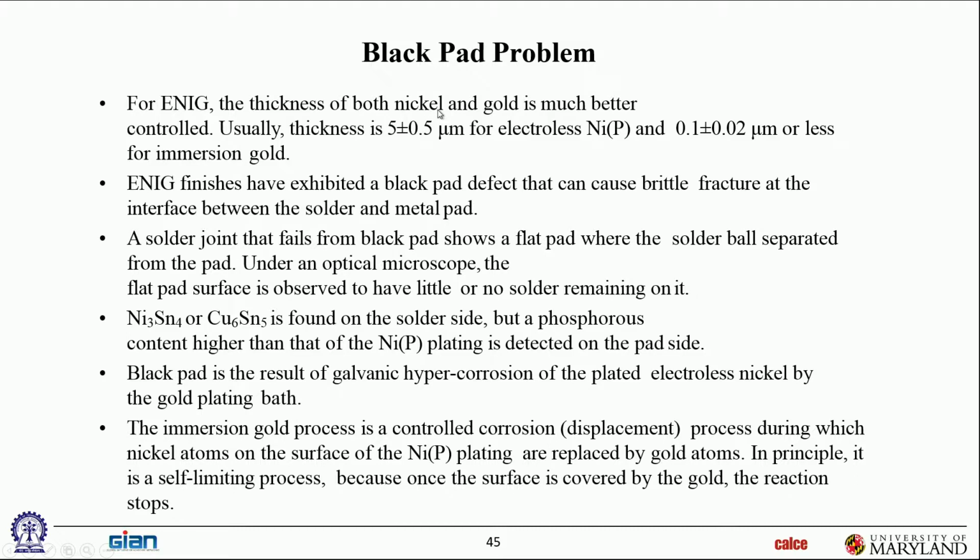We talked about the fact that we sometimes use, well, actually it's level 2 also, both. We talked about the fact that we use ENIG plating in a lot of cases. That's gold over nickel. And so this is electroless nickel, and there's phosphorus in the electroless nickel process. So it's a process chemical. It's not a lot, but it's sufficient to cause problems.